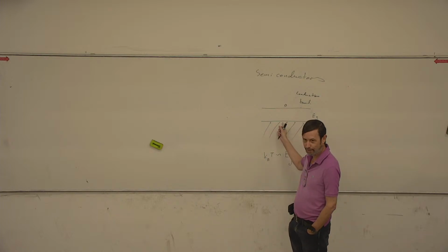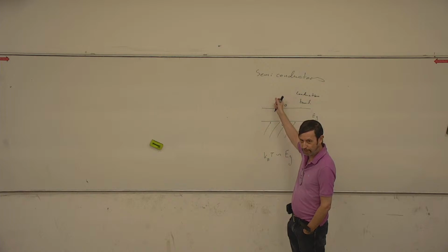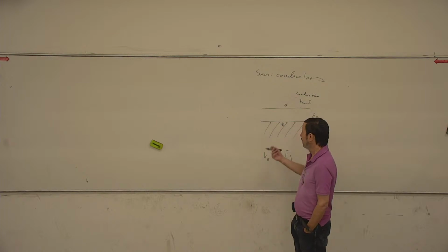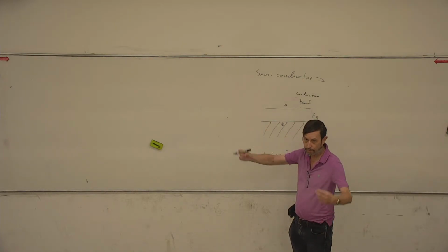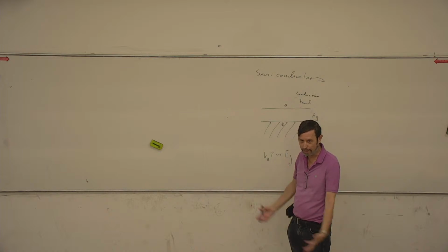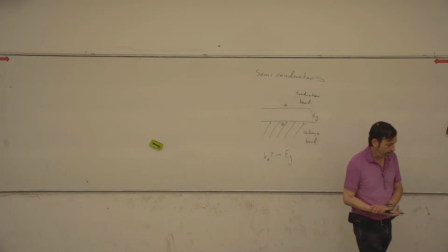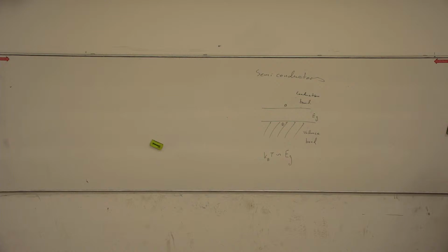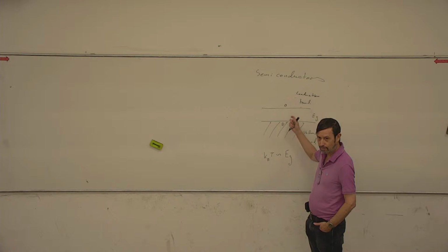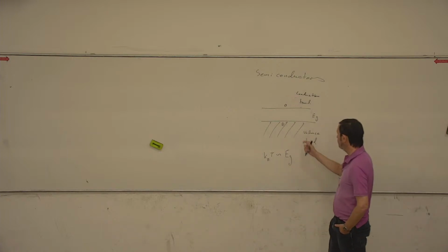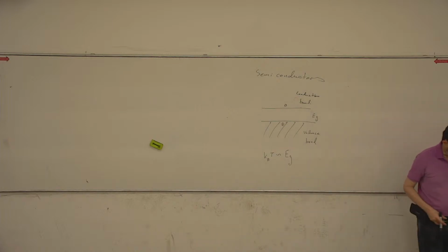I'm taking an electron from here, moving it to here, and I get an electron and a hole. It's not that I can't bring electrons from outside. Well, if I'm connecting it to leads, yes, but at the moment, we assume that all electrons that come into the game in the conduction band come from the valence band.